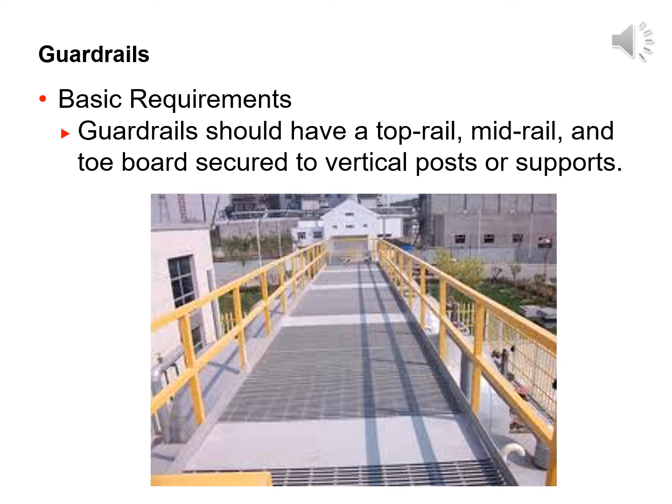When repairing or replacing guardrails, remember you're exposed to the very danger that you are providing protection against. You must be 100% tied off with a harness and lanyard if you are working within 6 feet of an unprotected edge.